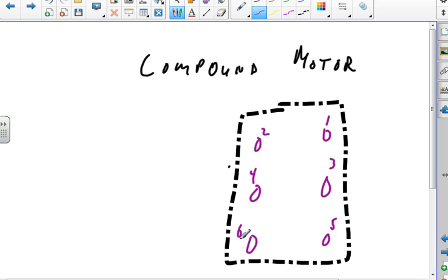One of them is a 5 horsepower motor that the carpenter guys have, the construction trades people have. They have a 5 horsepower motor on their table saw. And it turns out that due to the configuration of motors, you would want to start a motor in Y configuration and then have it run in delta for your most efficiency. So you have 12 different wires, and you wire it so that it starts Y, runs delta.